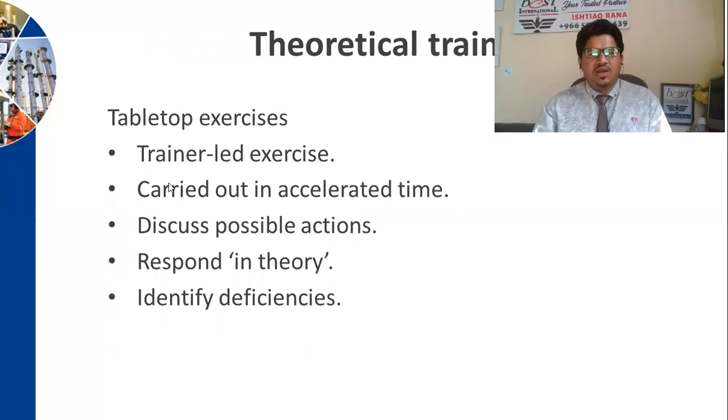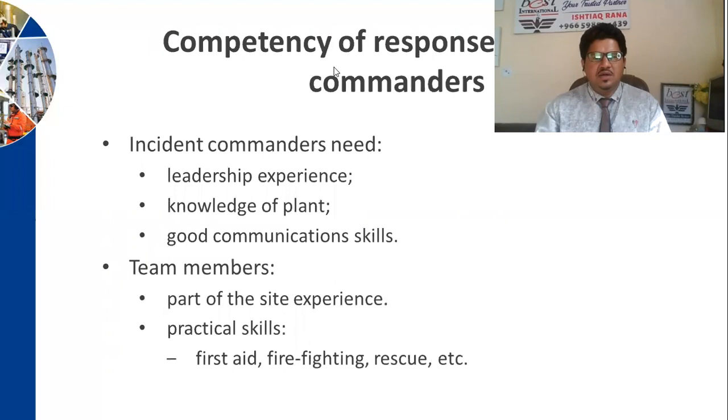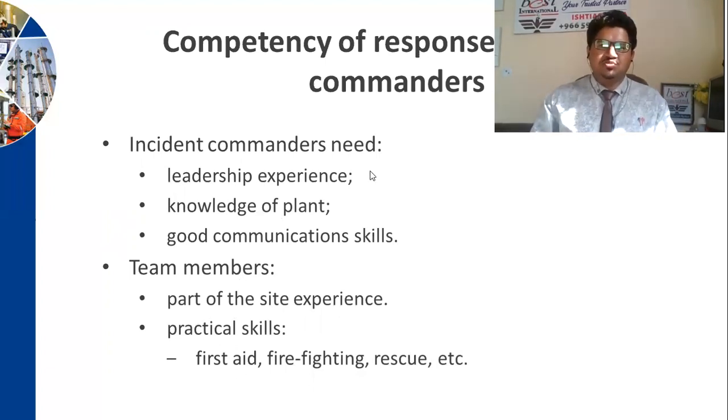Now, theoretical training: tabletop exercises can be done, trainer-led exercises, carried out in accelerated time, discussing possible actions, responding in theory and identifying deficiencies, and the competency of the response team and commanders. Make sure you have incident commanders. They need leadership experience, knowledge, and good communication skills. Team members need site experience, practical skills, and first aid. Firefighting and rescue team members must be part of this team.